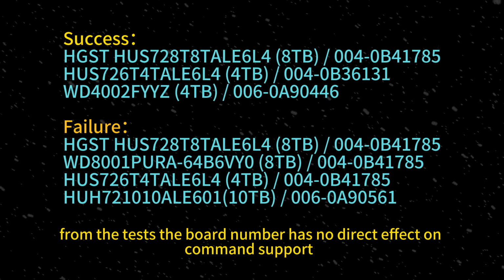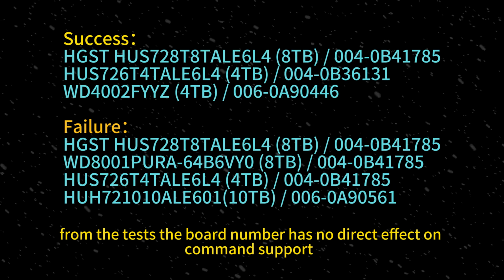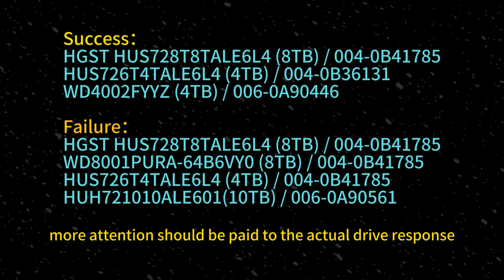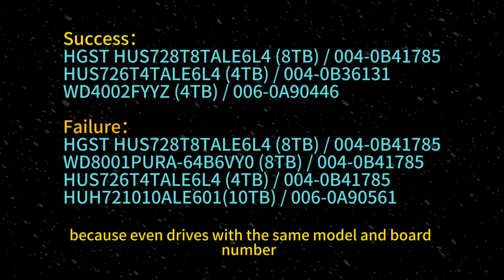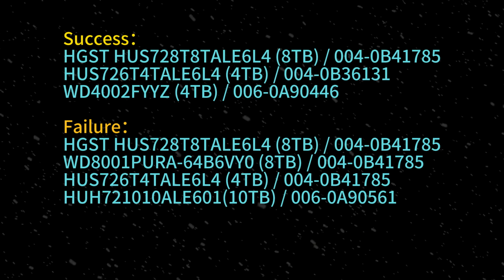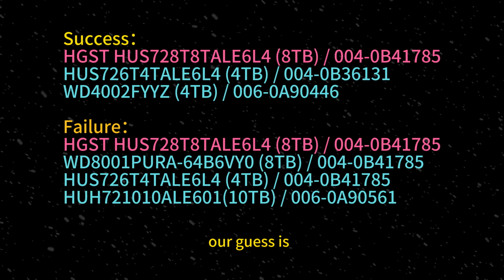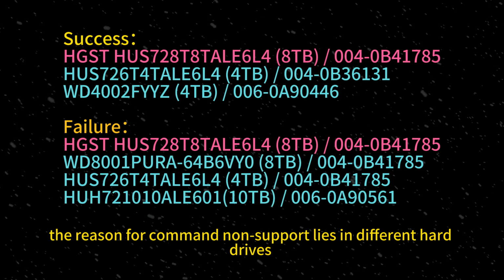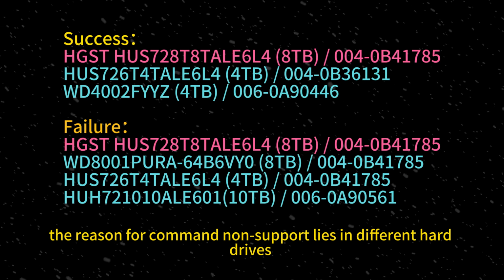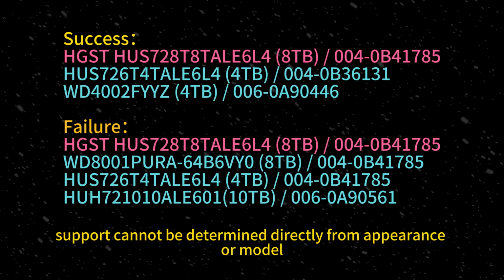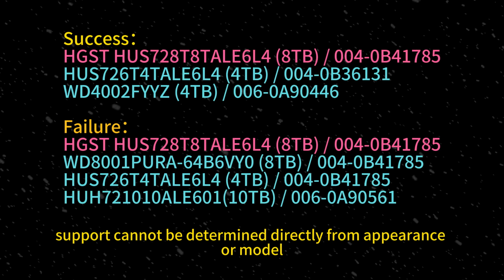From the tests, the board number has no direct effect on command support. More attention should be paid to the actual drive response, because even drives with the same model and board number, one may support the command while another fails. Our guess is the reason for command non-support lies in different hard drives responding differently to the instruction set. Support cannot be determined directly from appearance or model.